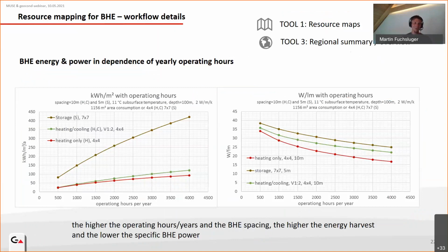Some more details I prepared, which I think are really interesting, because you see here 2 graphs. The left one is the borehole heat exchanger energy, and how it depends on the yearly operational hours. You see 3 modes: heating only, heating and cooling, and storing. For storing it's much more than for heating and cooling, because the spacing is 5 meters and not 10 meters.